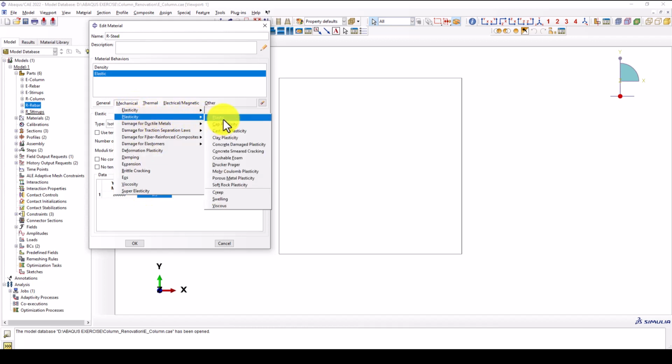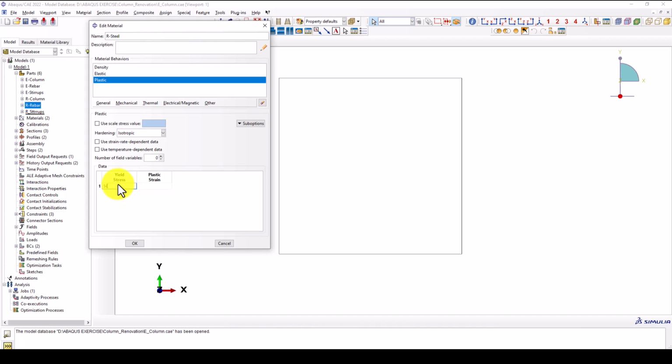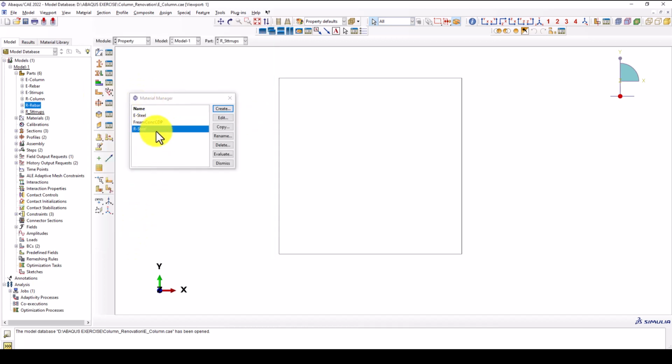The plasticity is, as we already mentioned, starting at 0 plastic strain, and then we give the ultimate, which is about 1.3% of this one. I can add one more cell or row, and give 475, and it's almost 23% plastic strain. So this is a simple steel material.